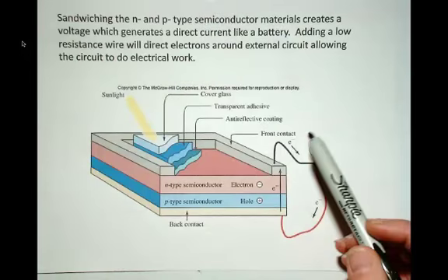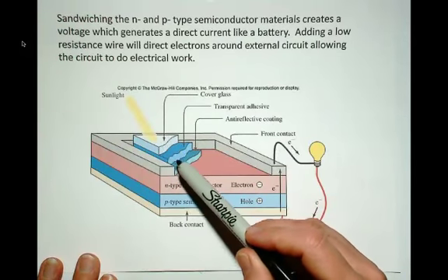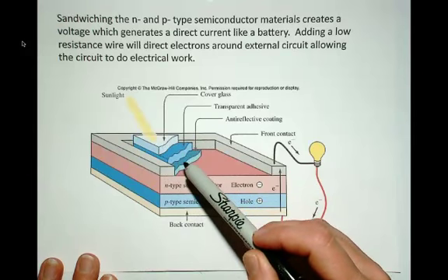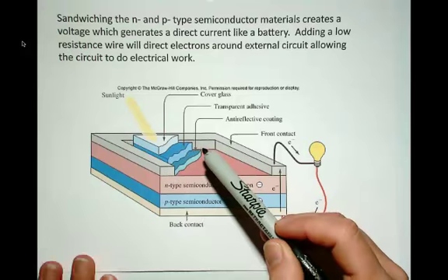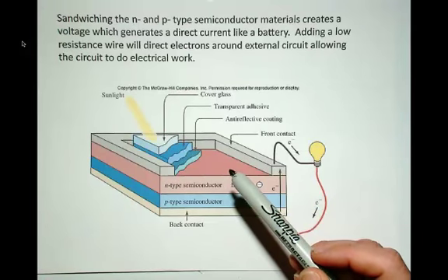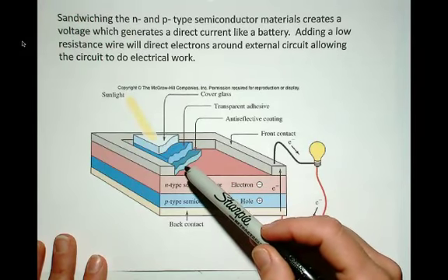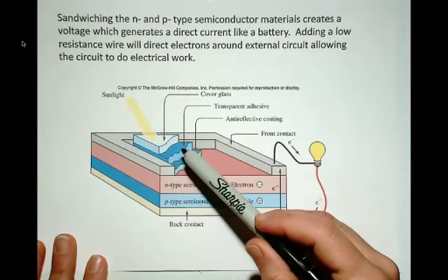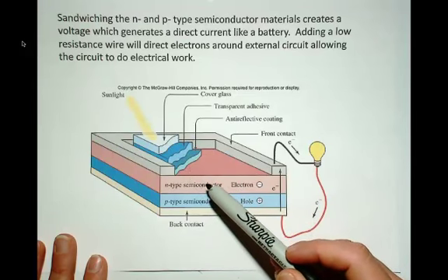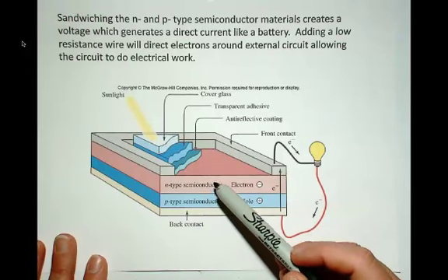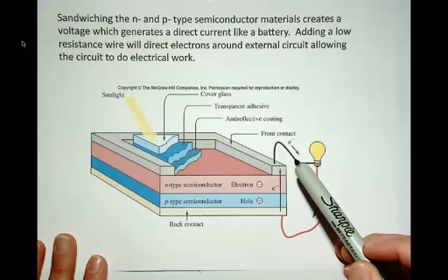So this would be a sandwich of just the glass plate on top to protect the whole thing, and then something to hold the glass on, some sort of adhesive, an anti-reflecting coating, because the light that's reflected or absorbed and turned into heat is not going to be used to move electrons around, so you want to try to maximize the efficiency there by reflecting as little of the sunlight as possible, and then the sunlight hits the N-type, and then gets the electrons moving.